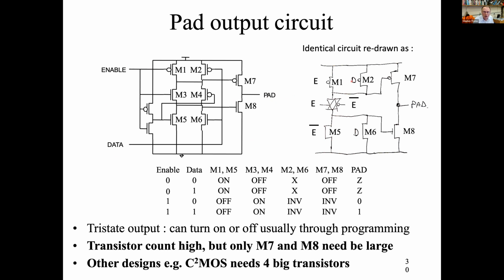We've also got the same circuit. Okay, so this circuit here, I've just redrawn here. So you can see the same transistors, M1, M5, and so on. The M3 and M4, between them, simply form a pass gate. So that's been drawn as a pass gate with our enable signal. So the enable signal here can either be high or low, and this clearly will either enable the pass gate, or the other way around, disable it. So it's not a pass gate, it's a transmission gate.